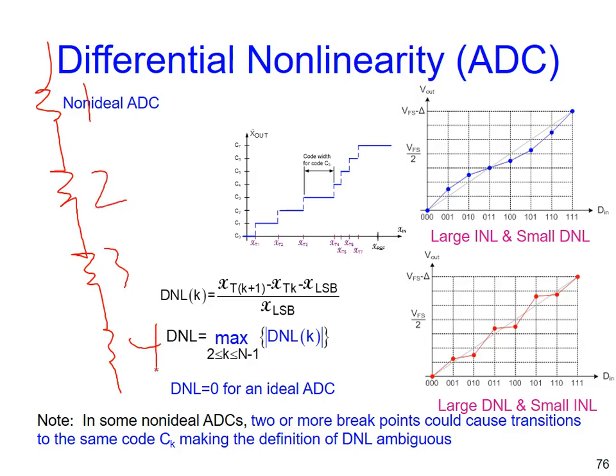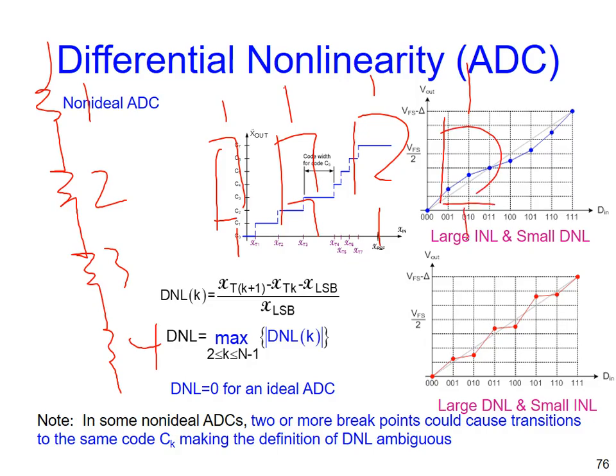Okay? Don't be silly. During your layout, the resistors here, right? And then, usually, if you are lazy, intuitively you will say, oh, the first, the second, the third, the fourth. Is it good? No. According to systematic mismatch, if I am larger than expectation, all my neighbors are more likely to be also larger than the ideal value.